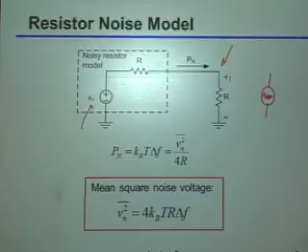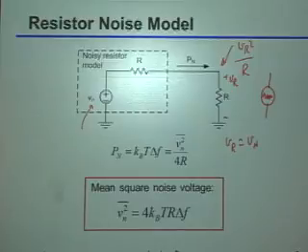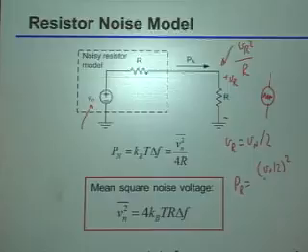Okay, you said that if I told you what this voltage was, then the power that's dissipated there is V squared divided by R, right? Okay, so what is VR as a function of the noise voltage Vn? And I obviously didn't write the whole equation there, so don't assume that they're equal. Yeah, it's 1/2, right? You just have a resistive divider. Okay? So that means that the power that's dissipated on that fake resistor is essentially just (Vn/2) squared divided by R.